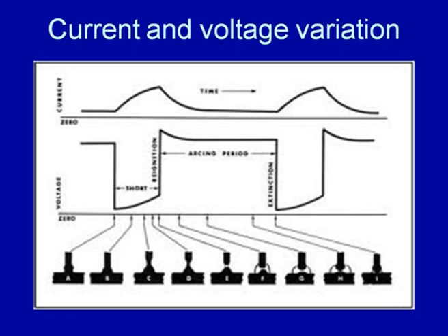So, these are the stages through which the molten metal drop at the tip of the electrode starts to grow, and this growth continues. In these 3-4 stages the molten metal drop grows to such an extent that short circuiting takes place again, there is a sudden drop in the arc voltage, and there is a gradual increase in the welding current, and this kind of cycle keeps on repeating in this mode of metal transfer.